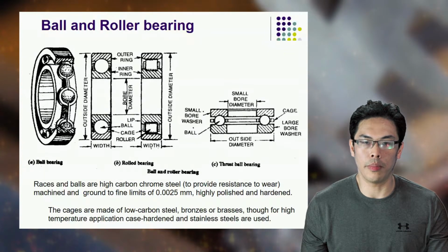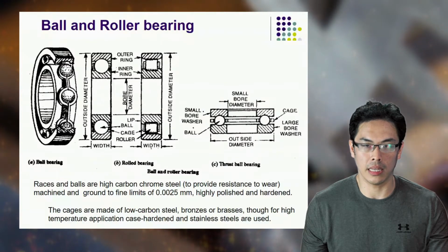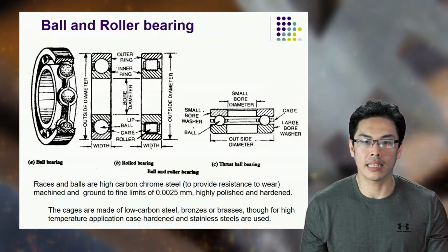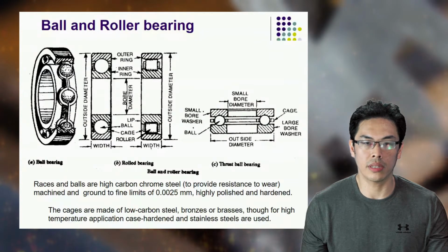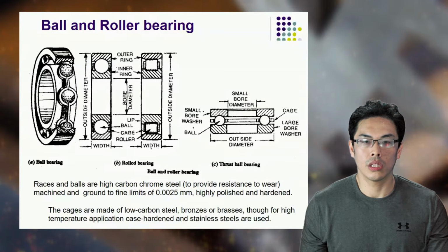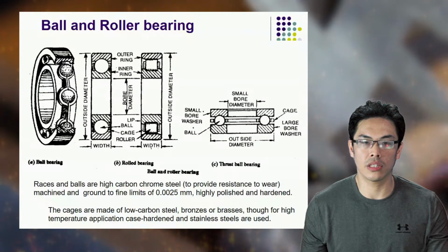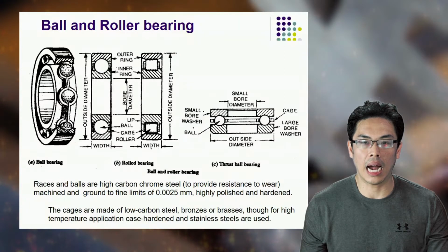Single row roller bearing. Roller bearings have a greater load carrying capacity than ball bearings of equivalent size, as they make line contact rather than point contact with their rings. Not suitable for axial loading. Cheaper to manufacture. Used for heavy and sudden loading. High speed and continuous service.